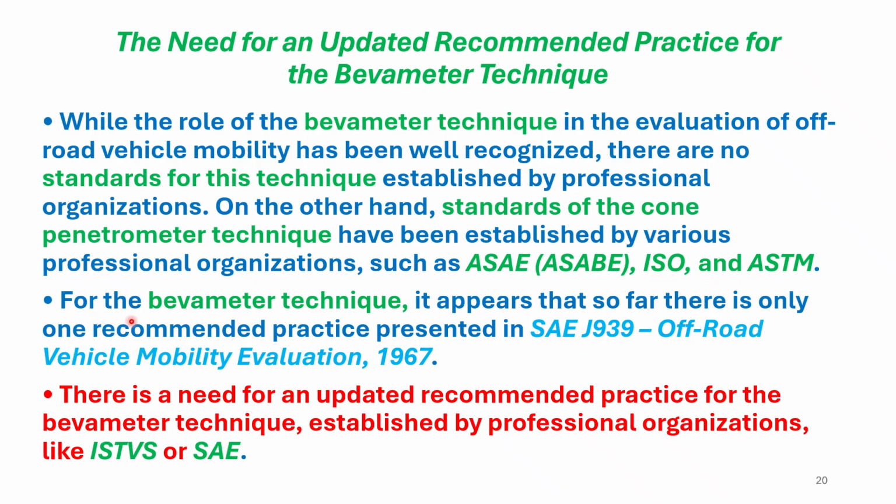For the Bevameter technique, it appears that so far there is only one recommended practice presented in SAE J939 Off-Road Vehicle Mobility Evaluation of 1967, almost 60 years ago. There is a need for an updated recommended practice for the Bevameter technique established by professional organizations like ISTVS or SAE.